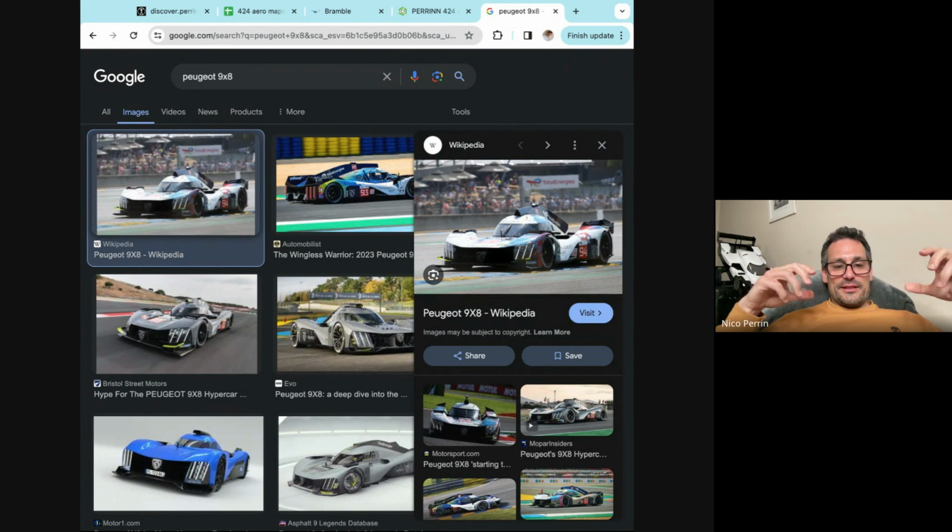And they said, okay, we can counteract this by having an aero balance that will be more to the front, so a 50-50. So we need to use big front tires so that we can use that aero balance, a bit like the Nissan LMP1. But when you do that, a race car is not meant to be 50-50 with the same tires front and rear, because you're going to struggle to warm up your front tires, because there's more power at the rear, and the power on the drivetrain will warm up the tires naturally at the rear. So you end up with a very split temperature front to rear tires, and the front don't work, and you've got understeer. So you can see the aerodynamic concept has dictated the mechanical vehicle dynamics, and in the wrong way.